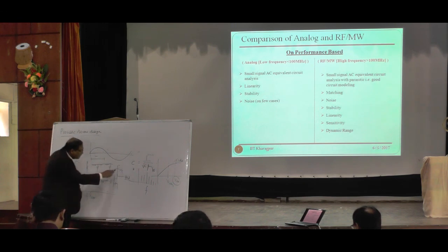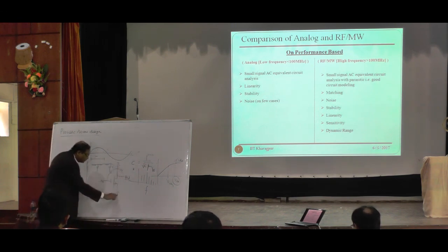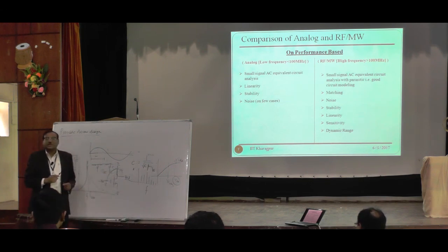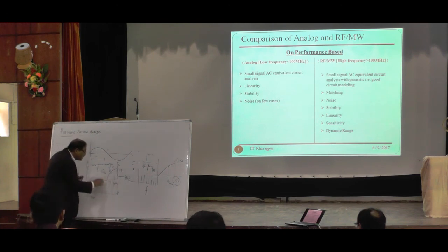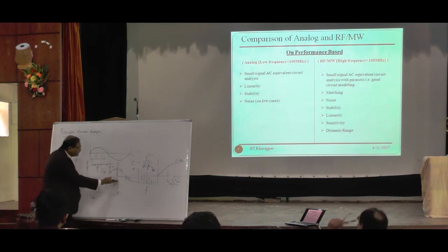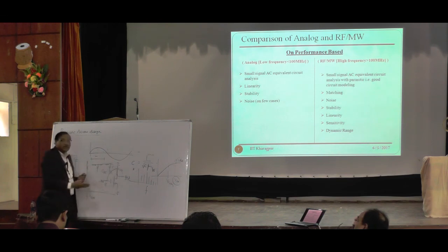So what is the culprit for oscillation? It's C, this is the drain, this is the source, this is the gate. So C, D, G. A fraction of the output will come through this capacitance. You may not be knowing the parasitic capacitance, but that is the finite capacitance which tells you that some kind of oscillations might build up.